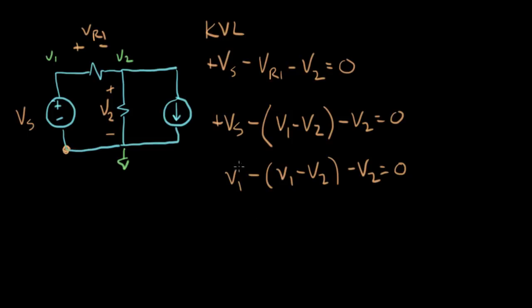And if we look at this equation, that goes plus V2 minus V2. This equation is automatically true if we write Kirchhoff's current law in terms of node voltages. That always turns out to be the case. That's why we don't bother to do it. We know it's going to be true. So that's a nice feature of the node voltage method. It's a really efficient way to write equations. You only write KCL equations. And this is such a good method, in fact, that circuit simulators, like you may come across a circuit simulator called SPICE, almost every circuit simulator uses this node voltage method to do its computations.